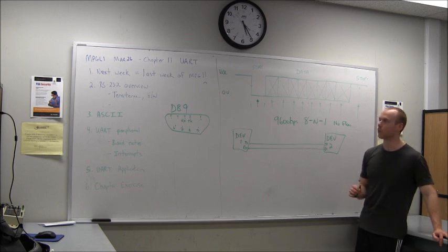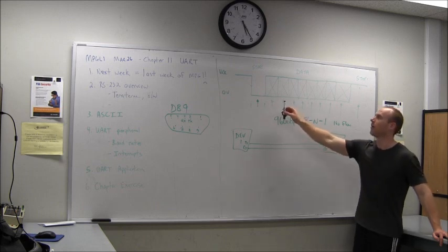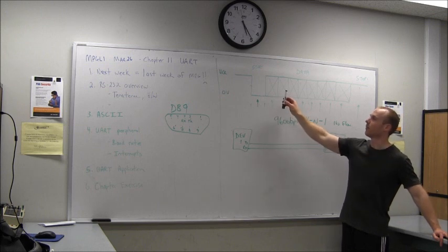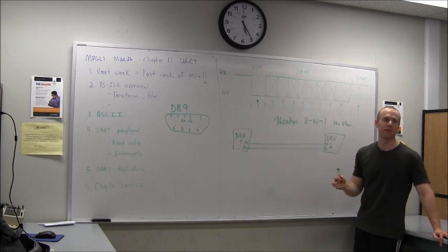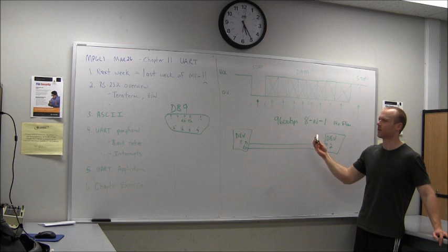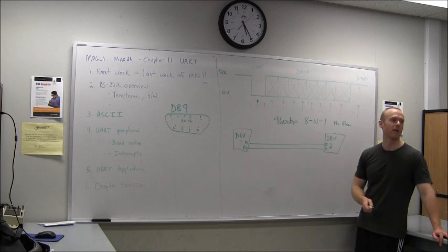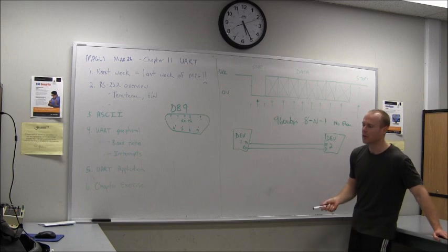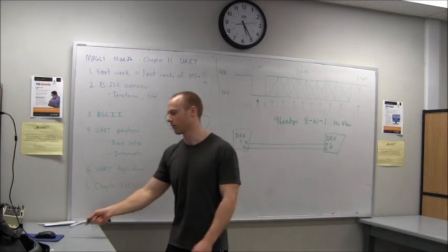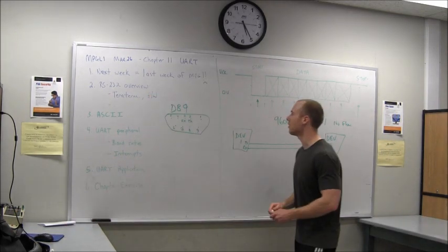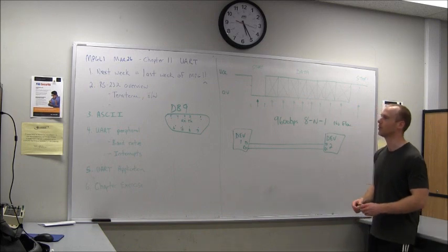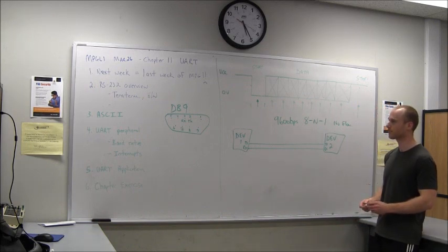Some different peripherals work in different ways. They might try and take best of 3, they might do an edge detect, they might do a whole bunch of different things. I don't know if this one even comments on the ARM processor how it works, but a lot of them do just assume that the one sample that they take in the middle is correct. But if you have noise and stuff like that, then you can have some problems. So there's a bit more discussion about all the different issues that can come up with this sort of communication. Okay? There's not that many.